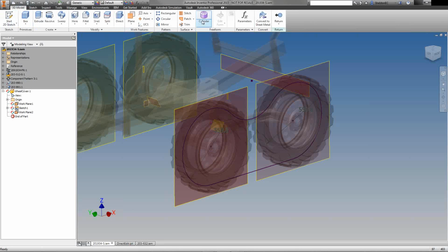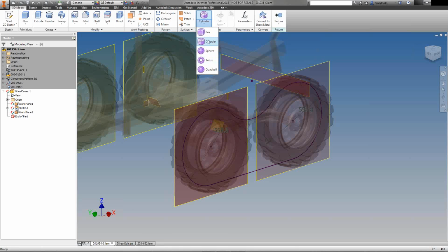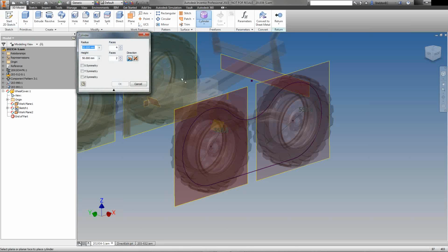Okay, so I'm back on the 3D model tab, and we've got a series of fairly standard freeform elements. Now these are actually creating solids, but they edit the same way that a surface modeler would edit. Okay, so they're quite intuitive, very freeform, easily manipulated, and they're a little bit like the old primitives dialog box that we had in the solid editing mode. So I'm going to create 2 cylinders.